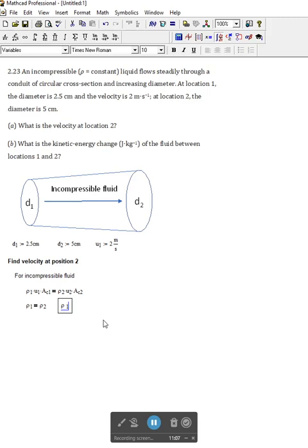Now, to assign a value algebraically or symbolically, I use Control Enter. And that gives me that bold equal sign. And then rho 2 is R, Control G, dot 2. So that's how that is entered.